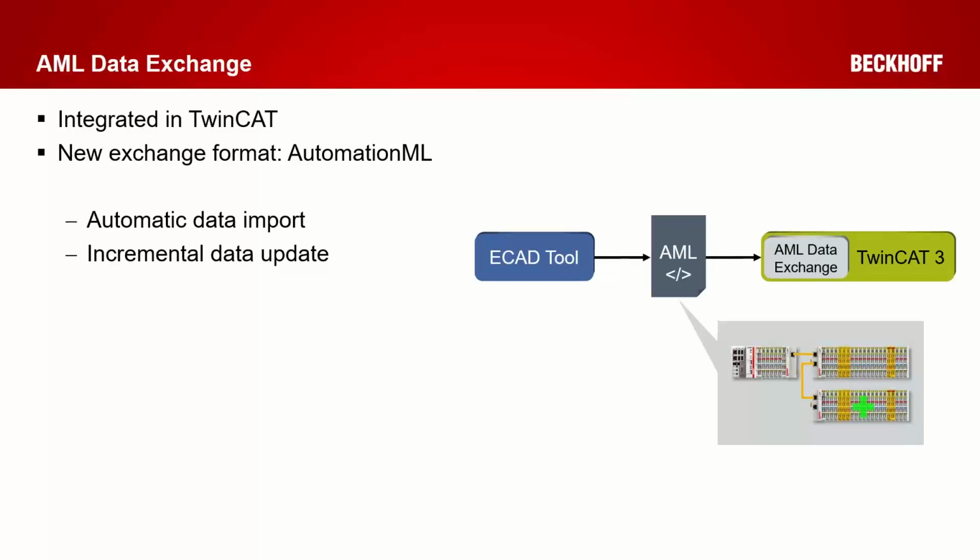In this case, the TwinCAT project compare tool is opened automatically. And as each of the components has this unique ID, it is possible to compare the two topologies and add new items, for example, delete old ones or rename items.